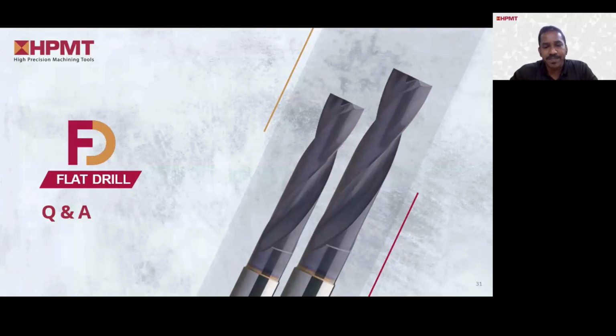Okay, I'll give you some idea. Generally, the materials we mentioned are the suitable materials, but the missing materials are only two groups in ISO. One is H, another one is super alloys. When it comes to H, we are talking about more than 50 HRC. It's not recommended. Any steels below 45 HRC are suitable, or the flat drill can be used. Another one is super alloys. When it comes to super alloys, like titanium or Inconels or even difficult-to-cut stainless steels, below 35, 36 HRC is also suitable. So this is the general answer to your question.